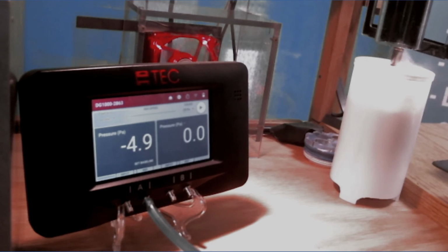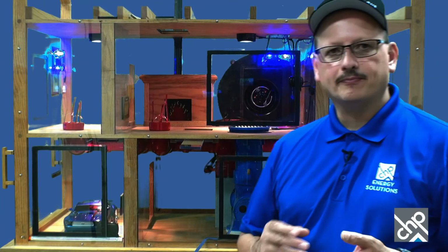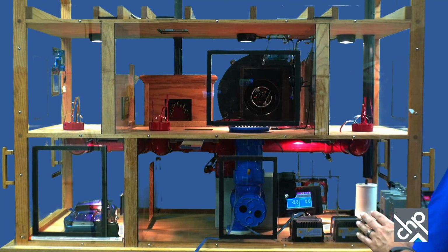So figuring out what made the pressure change that caused the backdrafting, was it the exhaust fans, door closure? And in this model it's basically that central return. If I put duct leaks in it, I could cause problems like that and create all kinds of different scenarios. So now turn everything off here.